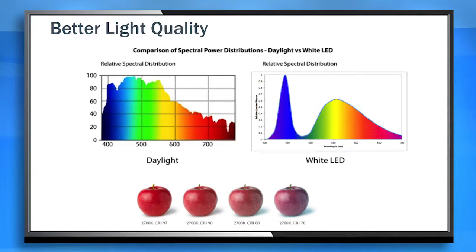Can you tell us then why daylighting is a better source? Sure. What you really want to think about with daylight is number one, all electric light sources are trying to mirror the lighting quality of daylight. I mean, daylight inherently has a CRI of 100, which is what all light sources are trying to achieve. The second thing is daylight is a full or broad spectrum light source. It covers the whole spectrum in terms of the color quality. Electric lights usually have points along those sources. They aren't able to provide a full spectrum of lighting. And the other benefit of using daylighting with electric light is that they're additive. You can improve the lighting quality of the space by simply introducing daylight with your electric lighting in a space.